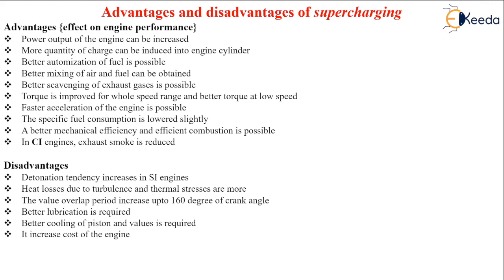Also, when the power output is increased, when the acceleration is improved, and when the torque even at lower speed is improved, this will demand better cooling and lubrication. So this might be a disadvantage if it is not provided properly, and also this will increase the cost of the engine. So this was some information about supercharging, its advantages, disadvantages, objectives, and its principle of operation.